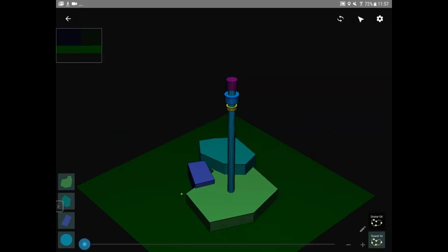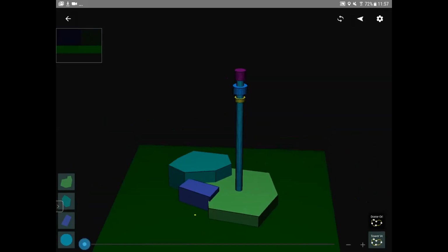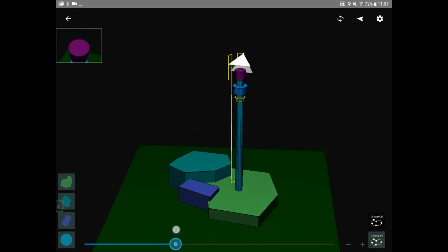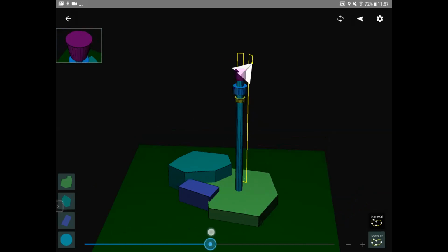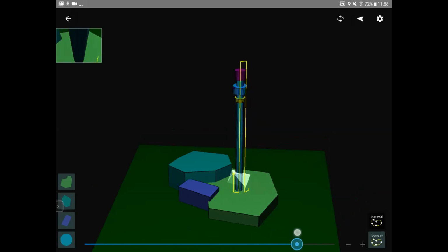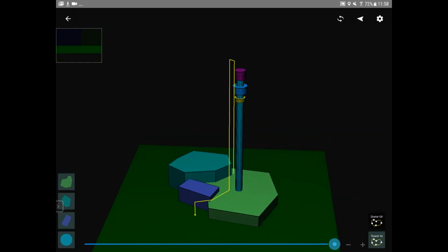So we have Tower Verticals chosen here. So let's see how a Tower Verticals mission might look like. So we're just simulating the mission. And you can see that I can simulate it by sliding over this slider from left to right. And you see that this mission flies up and down the tower and all around it. And here we can capture high resolution imagery this way. We can also capture video, but the more common use case is to capture images. And this kind of image set is very useful to cover the entire tower with very high resolution images that we can afterwards navigate conveniently, or to create a 3D model of the tower.